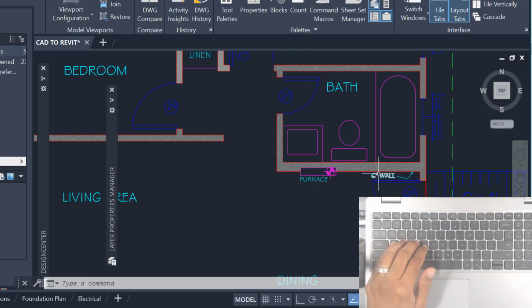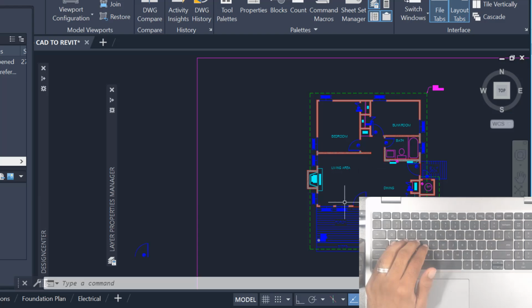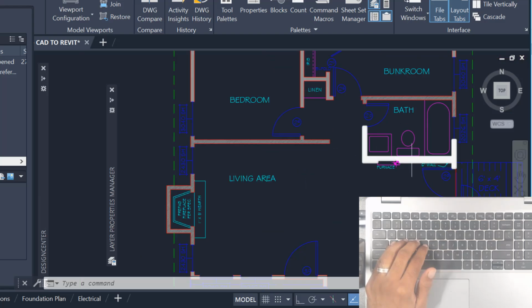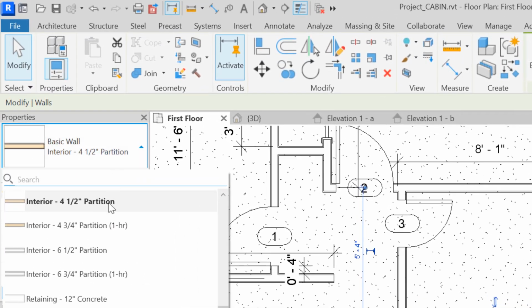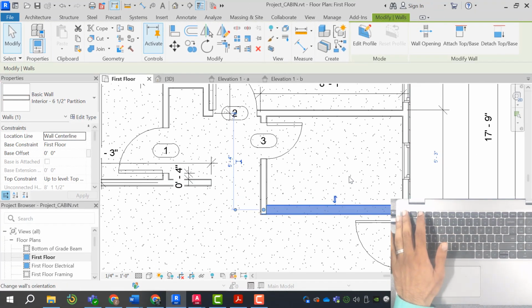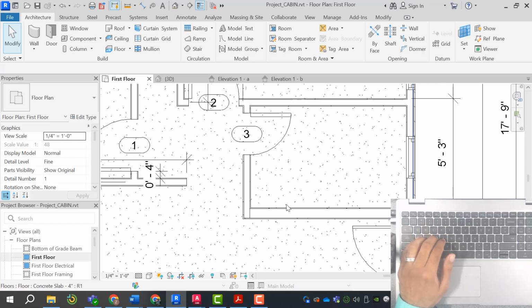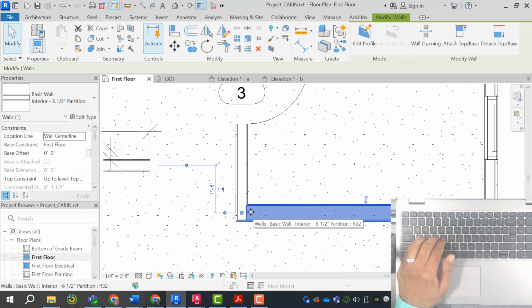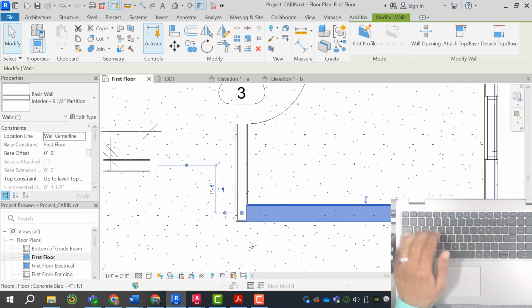So all of this being inside here compromises the wall structurally, so it's better to go with a 2x6, which I agree. I would also insulate this wall because this wall faces the dining room, which is probably not the ideal place to be hearing your toilet flush, but hey, it's a small cabin. Let's go to Revit. So I'm gonna go ahead and click on 6.5-inch partition, bumping up the wall size, and it kept the same interior dimension, but the interior dimension is viable to change based on the bathtub size.